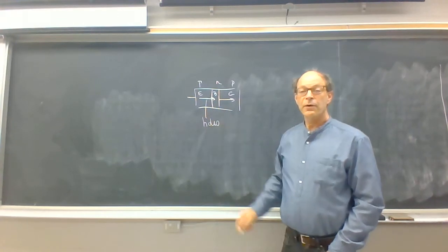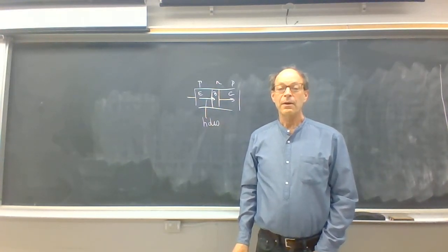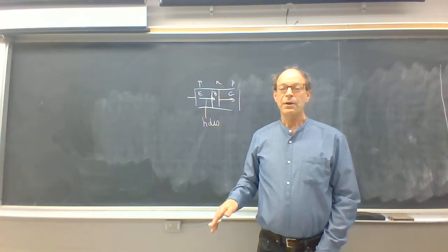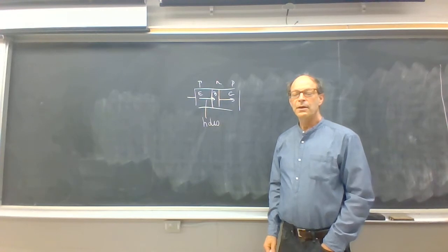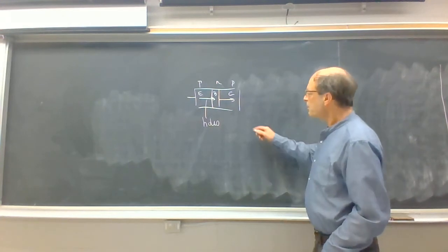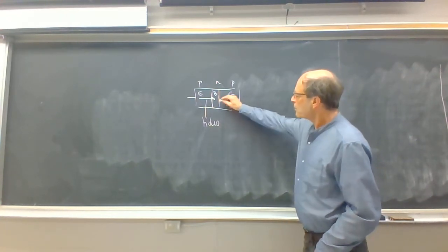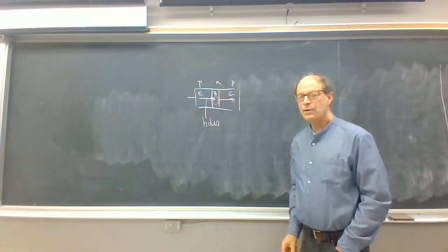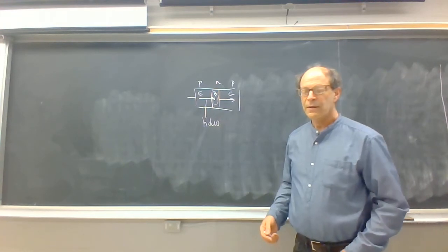And the diffusion of holes really relies on the holes not recombining. And so the base is made as narrow as possible, and in that way we can minimize the chance of recombination. So what will happen in this device is the current is flowing. We want to minimize recombination in the base. We have equations which relate to that.